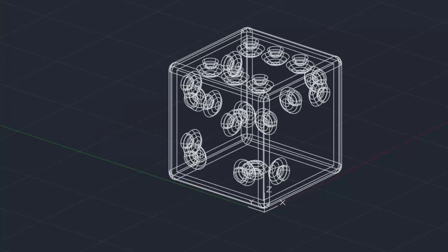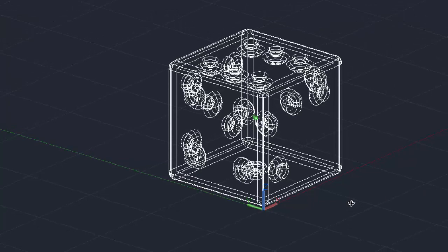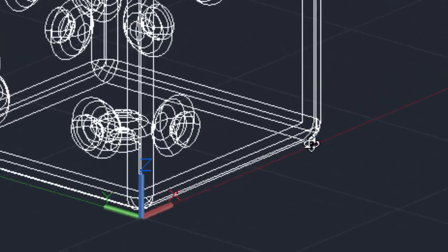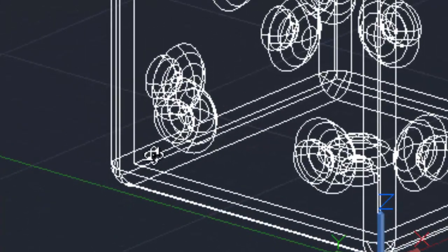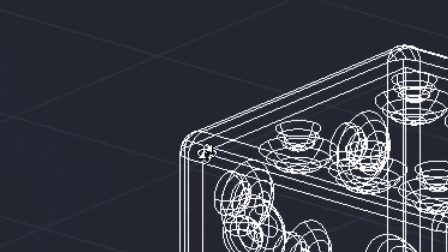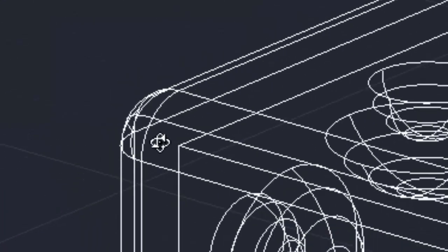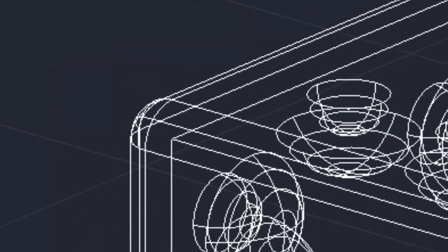Okay, so I'm just going to go down because I can't use my F9 key because of the recording software, and I'm going to turn my snap mode off. That way I can really get in fine to whereabouts these points are in here. So rotate it so that you can see this little point on its own away from anything else, this little point away from its own, and that little point at the very top in there. So we're looking at these corners. I'm going to do a diagonal slice.